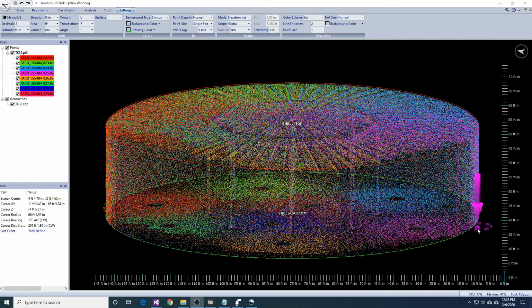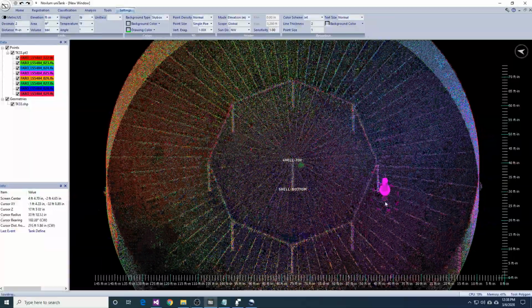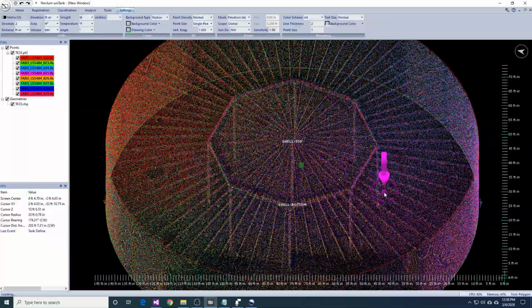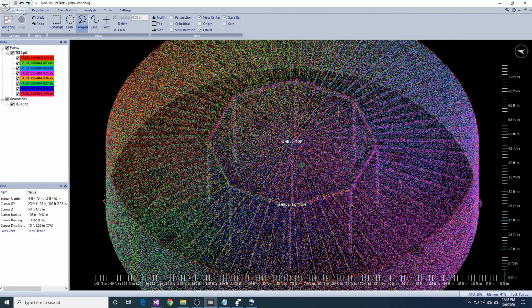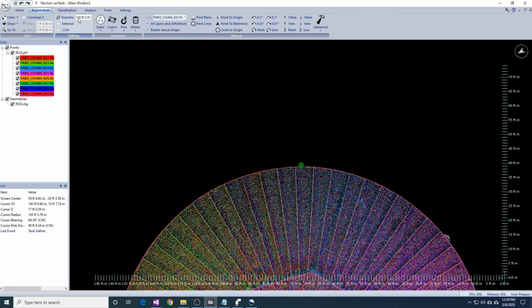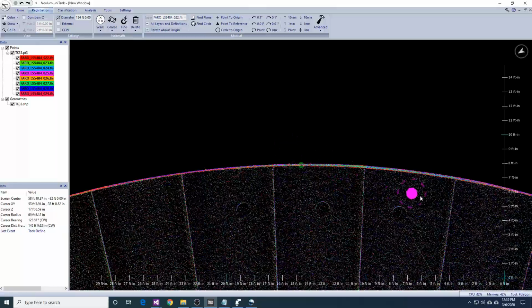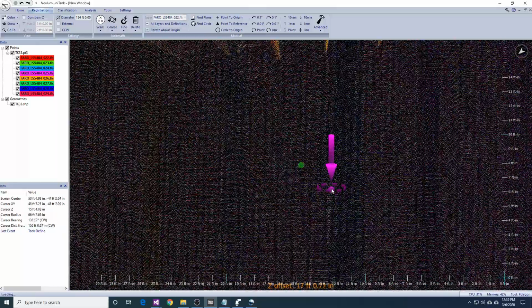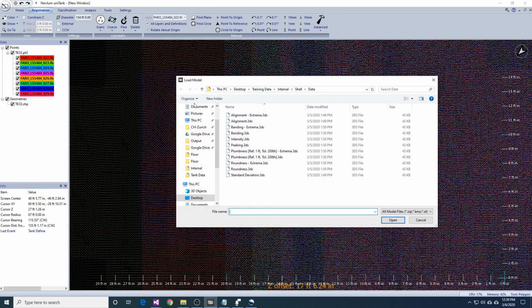of creating layouts. This part of tank analysis comes after you have completed the shell analysis, because we will use the outputs from this analysis to visually aid us in finding shell courses and plates. When creating shell layouts, you need to be in cylindrical mode. Make sure that the diameter in the settings is set properly so that the view center is focused on the shell. So first off, I will load in some of the outputs from the shell analysis.